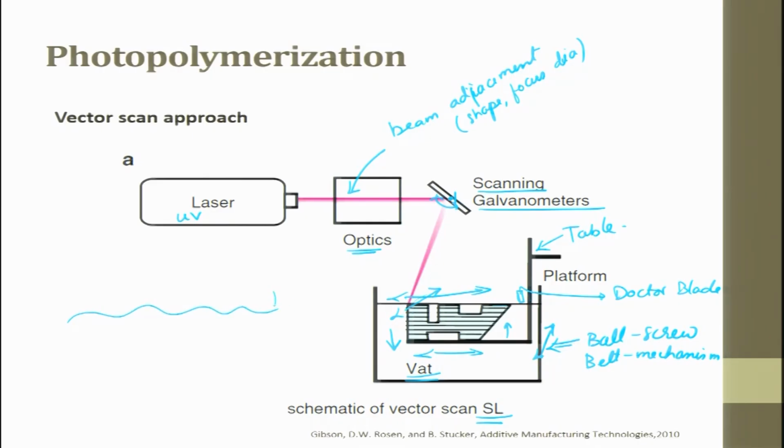So, this has to be nullified by a knife. When you move the knife, all the wave pattern which is there will be removed, and then you have a smooth surface for the laser to hit. Why? Because if you have a wavy pattern, when the laser tries to hit, there is a possibility it reflects. Okay. If it reflects, the efficiency of the process goes down.